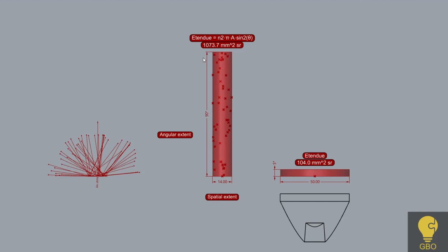The only apparent exception is if you're willing to accept a system efficiency well below 100%, say 10%. Technically, that would work, in the sense that the numbers would kinda balance out. But designing a lamp with a 10% efficiency just so you can pair an oversized LED with an undersized lens makes no practical sense.